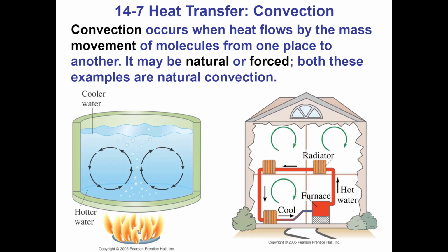Then hot water is driven up, and it could be forced, or it could be just gravity fed too. But that doesn't heat as evenly, and so we often have forced hot water. And so the water will go up into a radiator, and then the job of the radiator is again to make use of conduction and to warm the air around it. But then that warm air rises and brings cooler air in contact with the radiator, and it continues.